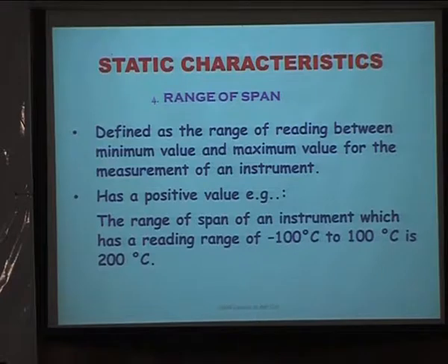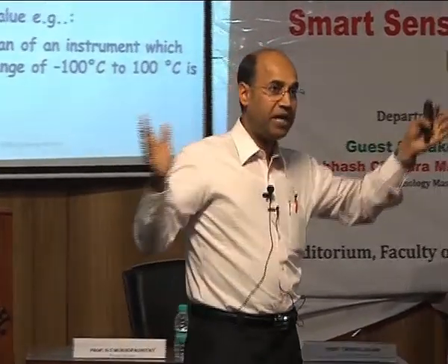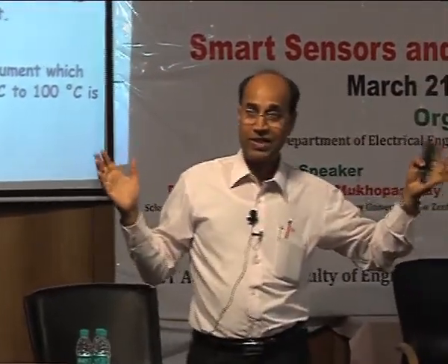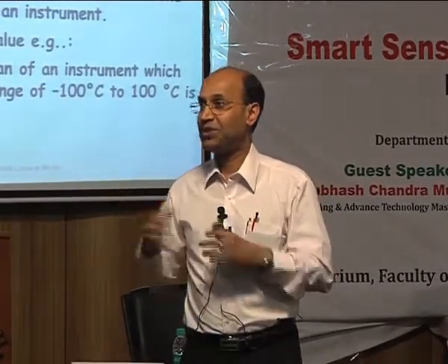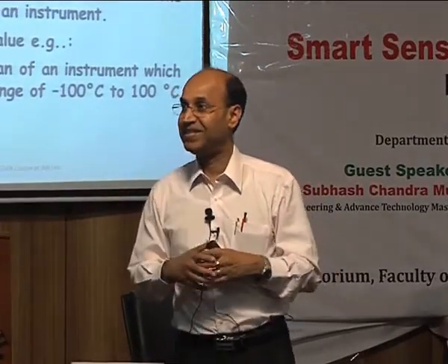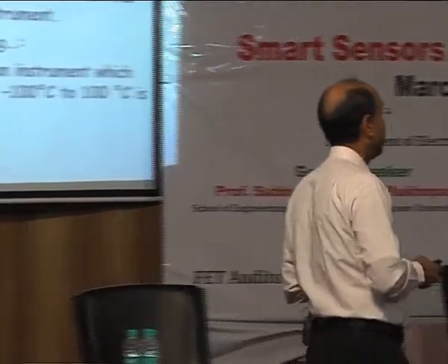So range is also something you need to know, what you are measuring. An instrument can give the capability of a very high value to a very low value. But if you express that as the error, you always get a very good error because your denominator is too high, isn't it? So you will again come to a different situation.